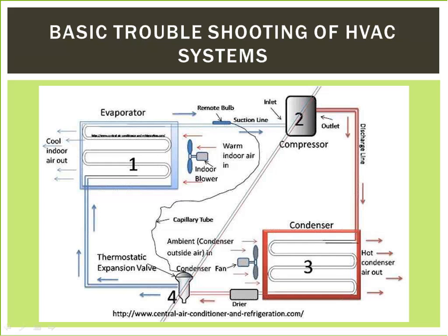The low side of the system should be cool to the touch, particularly from the metering valve going into the evaporator, which should be cold. Note that although it should be cold, it should not freeze or frost over. Most system evaporators will run around 40 degrees. The high side should be warm ranging to hot. It will be particularly hot from the compressor to the condenser. The temperature should become less hot as it moves through the condenser, but will still be warm until it passes through the metering valve. The fans should be running.